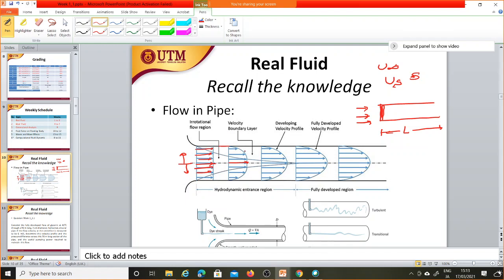It means the velocity boundary layer effect is much higher here, so we say this region belongs to the boundary layer. It means the velocity will keep changing. And if you consider the zone where the velocity change is not that much, close to the center line here, initially that zone where the velocity change is negligible is bigger, because it has just started, right? You can see that the line that separates the real and ideal zones is gradually reducing. So initially all of it is ideal, right?